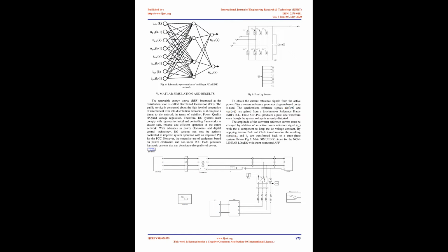Each of the active and reactive instantaneous powers possesses a direct component and an alternating component. The direct component represents the power of the fundamentals of currents and voltages. The alternating term represents the power of the harmonics of currents and voltages. To separate the harmonics from the fundamental load currents, it suffices to separate the direct term of the instantaneous power from the alternating one. A low-pass filter, LPF, with a feed-forward effect can be used to accomplish this task.